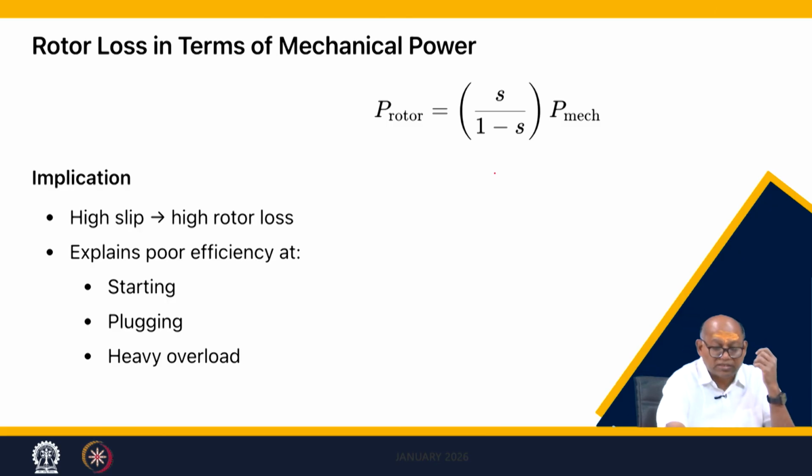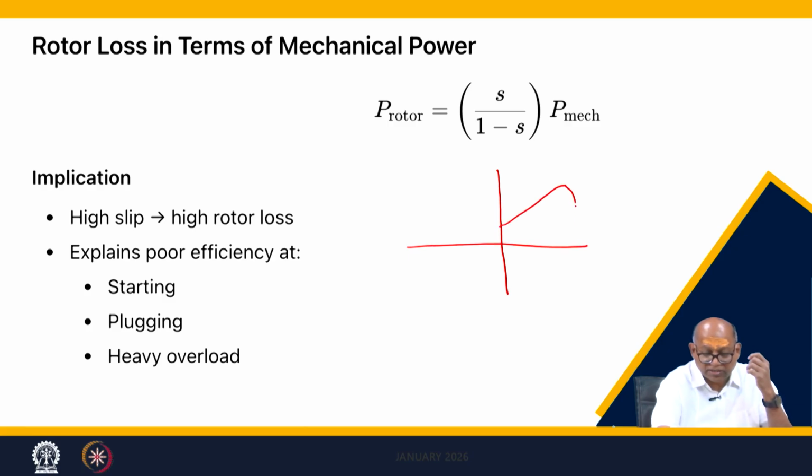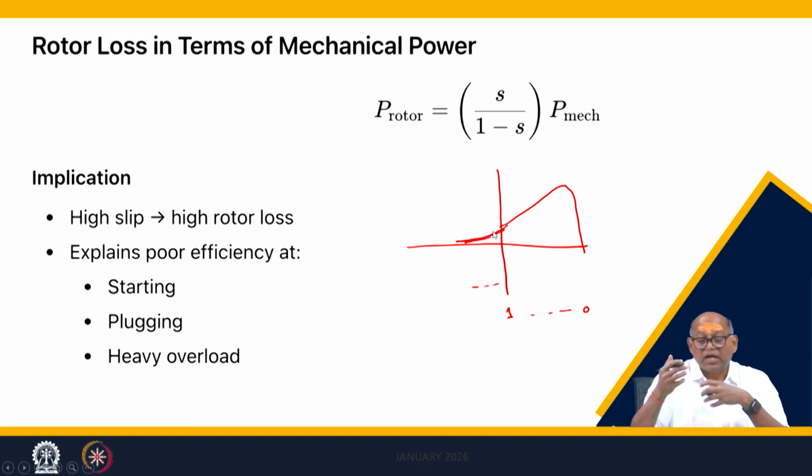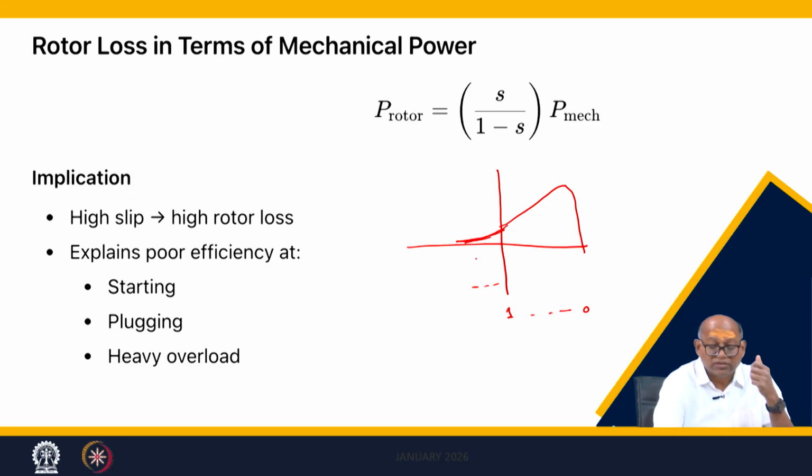This is the torque speed characteristic, you can see. When the slip becomes 1 here, the speed goes to 0. More than 1 means this way, so it will go like this. Here in this region, what will happen? In this region the speed is opposite and torque is positive. So there will be braking. This is called the braking region. We will see.